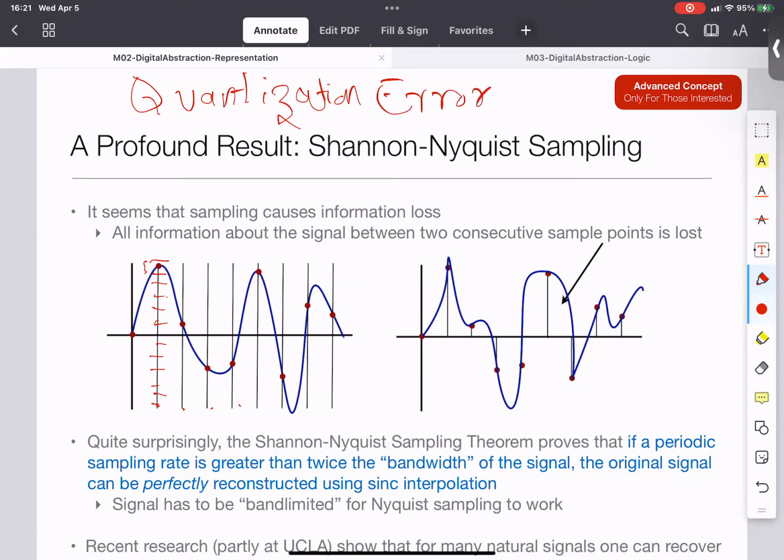Because what we are doing is taking a continuous value and dividing it into a finite set of values, and therefore there will be an error which corresponds, loosely speaking, to the size of the bin. That would appear to you as some sort of noise. Let's say it was a sound waveform and I digitize it like this. Then instead of my original analog sound, I'm introducing a little bit of noise in it. If I do it very crudely, the signal you hear would be very noisy. If I do it very finely, you won't.